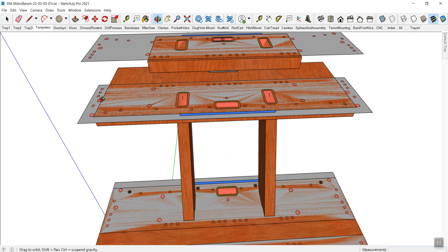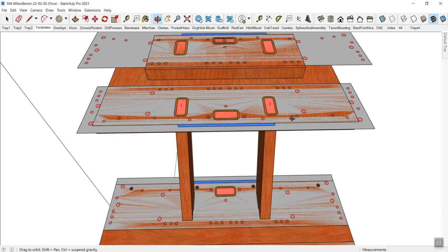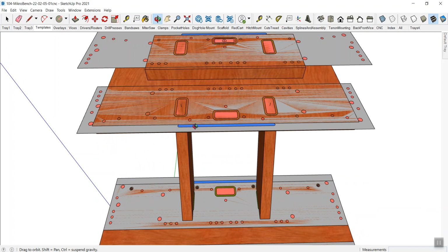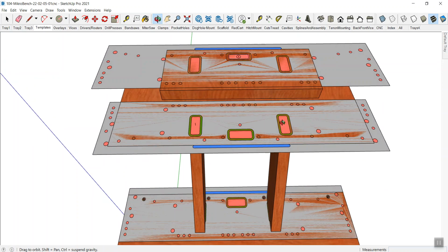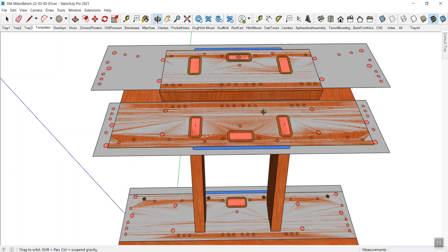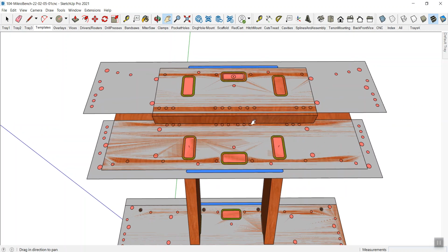So there's these 3/8 holes here, which are going to get 3/8 inch pegs when we use the template. And then that'll help align. So I'll have alignment in the front, and I'll have a bump on each side. That'll give me a perfect alignment on that board for me to run either routers to mortise those, or to create dimples that we're going to use a manual tool on.